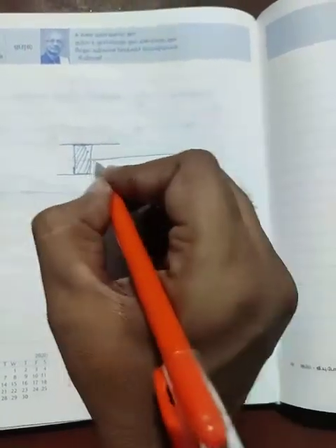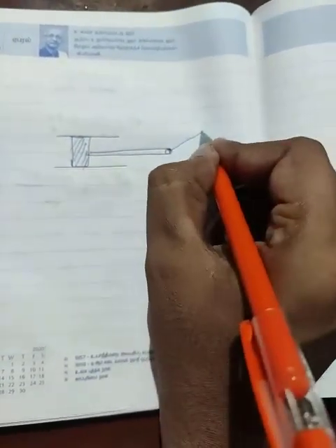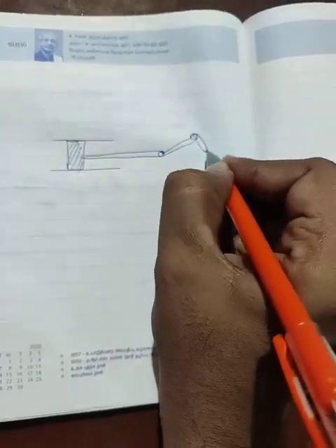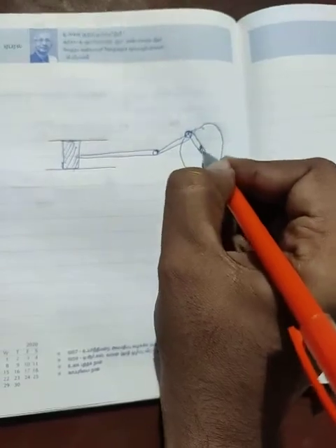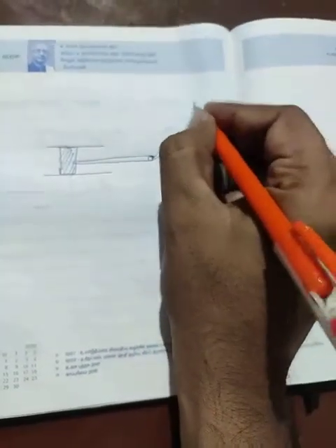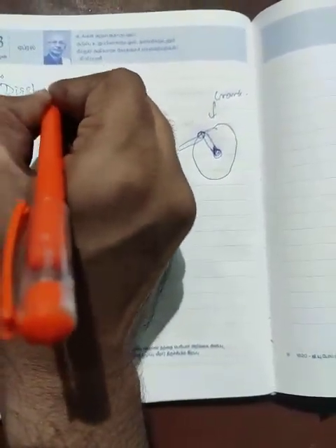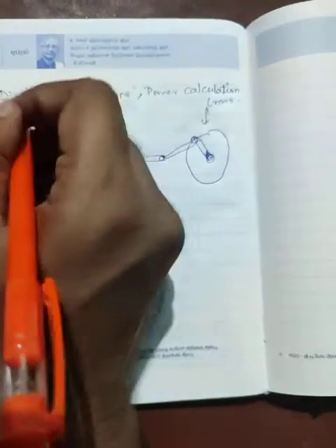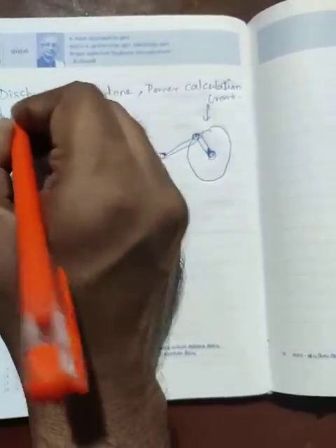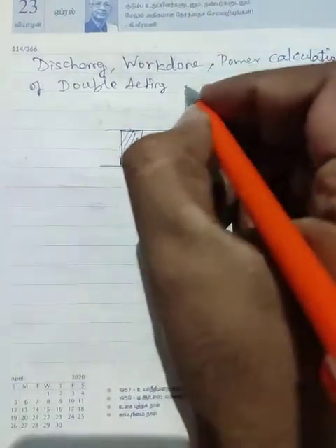So the topic of our tutorial today is the reciprocating pump. The reciprocating pump has mainly the components piston, connecting rod and crankshaft, which is driven by the prime mover engine. This combination of crankshaft and connecting rod converts the rotary energy given by the engine into reciprocating energy. This reciprocation is done at a piston, which sucks the fluid at one end and again delivers the fluid towards the upper side.